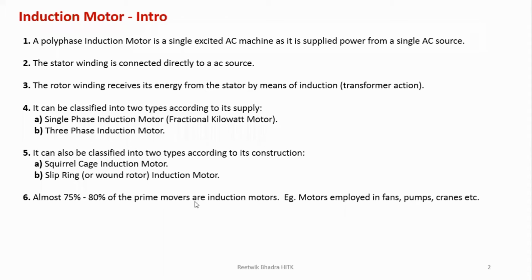Almost 75 to 80% of the prime movers are induction motors, meaning whatever is producing some mechanical energy, in most applications we use induction motors. Okay, examples: fans, pumps, cranes. In fans we generally use a single phase induction motor, because in our home all supply is single phase, so all fans at our home have single phase induction motors.